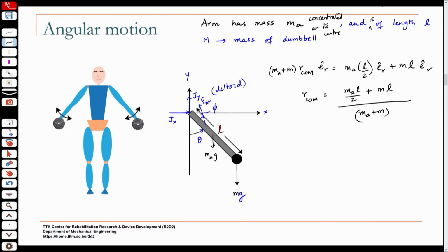Even in this case, when you substitute with the point center of mass, you will also have a moment of these two masses about the center of mass, which you will have to add. Yes, in this case you will have to calculate it. So it will be the moment about the center of mass of these two bodies, and then you will use the parallel axis theorem to compute it about O.